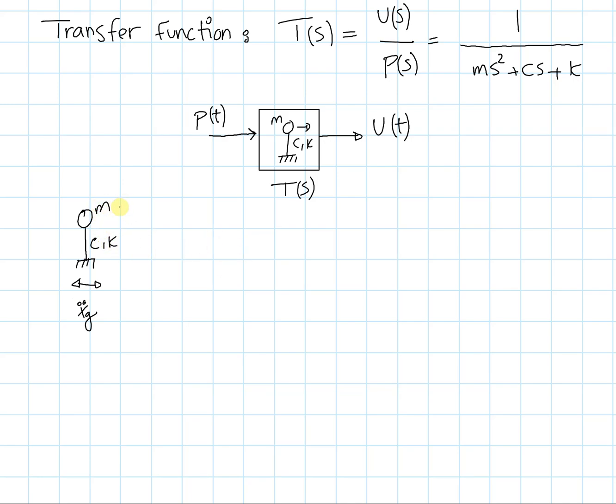We can write the equation of motion as follows. We have m x double dot plus x g double dot, which is the ground motion acceleration, because mass, or the inertial component, is always dependent on the total acceleration, or the absolute acceleration. So the total acceleration that this mass is experiencing is the motion of the mass plus the motion of the ground. So that's what we have.